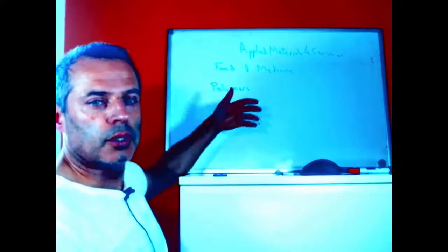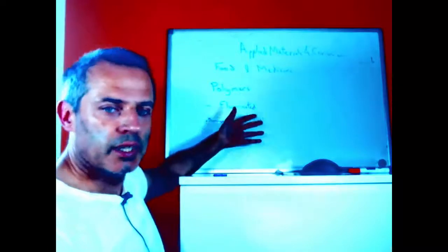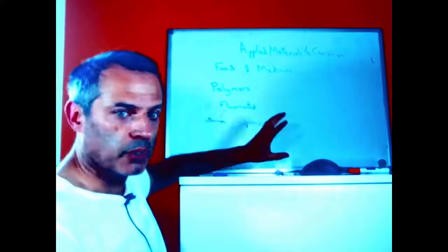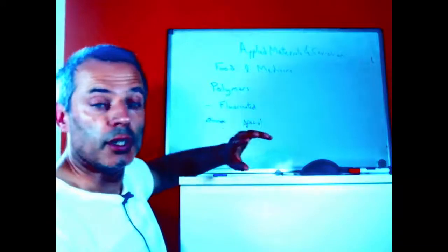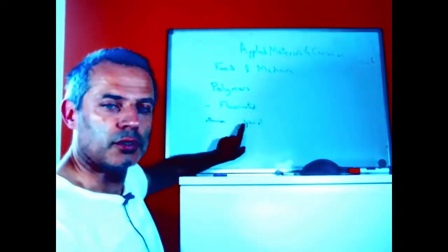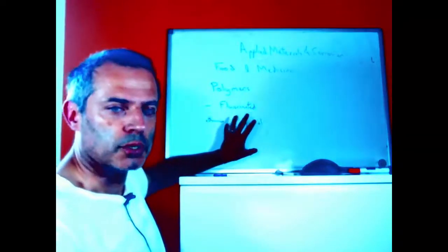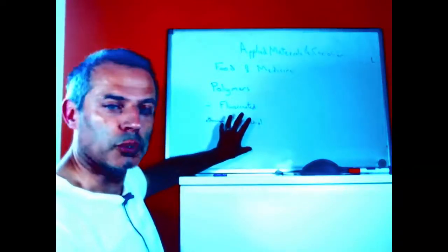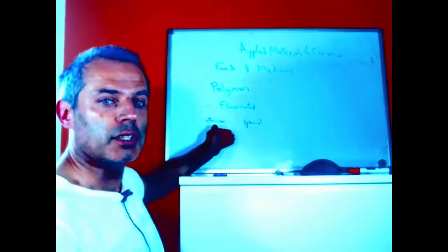If we use normal conventional polymers with a high enough melting point, then we can heat them up, but we will have to be careful. We may have to treat them specially. We do have to be aware of hydrolysis reactions that can happen. So nylon has a tendency to hydrolyze, but not a very high tendency. Some types of nylon are reasonably resistant if they've got enough hydrophobic groups on them. If we have a polyester, it becomes more and more difficult, and they tend to be used very little.